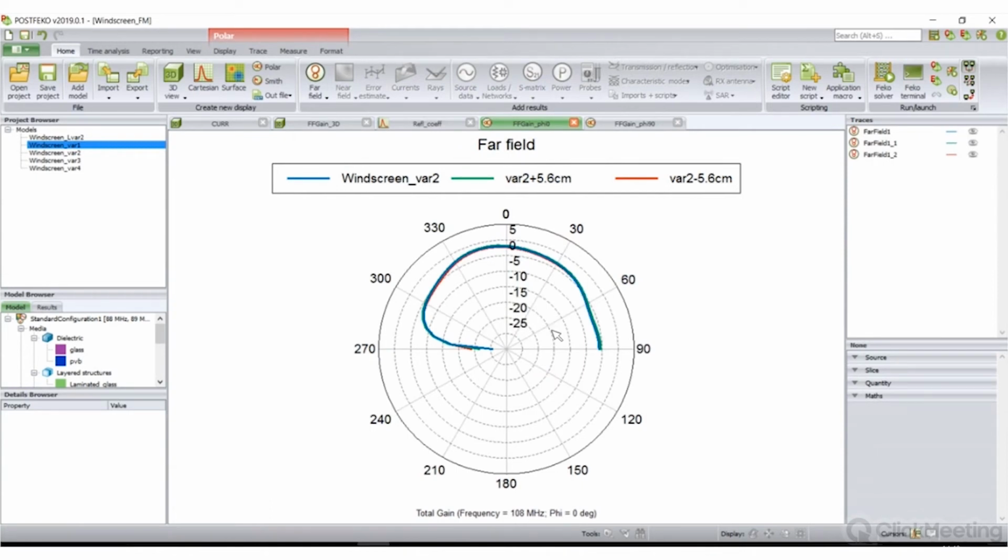Far field pattern. So as we can see, we have a pattern that is typical to the wire antenna pattern. Usually we would see a kind of a closed pattern that is closing itself out in here, but we can see the influence of the vehicle and of every steel plate that is around our antenna.